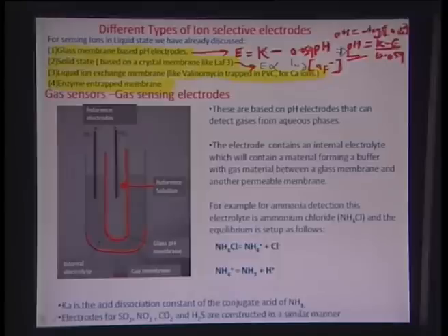Okay. So, this is typically, if you may recall, the silicates or chalcogenides or group 6 metals, which are able to select specifically hydrogen ions over the other interfering ions. So, here also we have another reference solution in this particular zone. You have a solution inside the glass membrane for the hydrogen ions, and a solution outside it, and we have two electrodes here, Re1 and Re2, which are both reference electrodes, and they would be able to sense any transfer of H plus ions into the internal electrolyte here. So, essentially you are trying to detect the change in pH, and how that is related to the analyte of interest is reflected below in the following area of the slide.